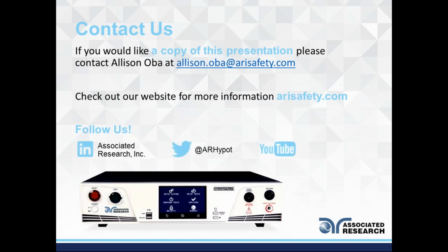So go ahead, Syed, we have a question. How often should I recalibrate my Hipot tester? Sure. So the question is, how often should you be recalibrating or calibrating your Hipot tester? Well, as a manufacturer of Hipot test equipment and electrical safety test equipment, Associated Research recommends a yearly calibration to ensure that all the data points on your instrument are within tolerance limits and it's meeting the specifications that we call out for.